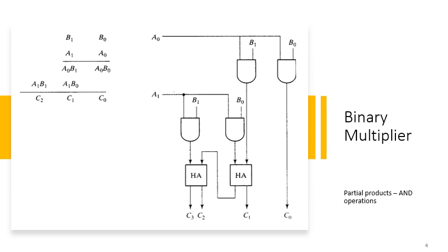B0 and B1 are collectively known as the multiplicand, and A0 and A1 as the multiplier. So how are we going to perform the multiplication? The same principle used for decimal numbers applies to binary data as well. First, A0 is bitwise multiplied with B0 and B1 to produce the product terms. When A0 is multiplied with B0, the first term is A0 B0. Then A0 is multiplied with the higher bit of B, that is B1, so the product term is A0 B1.